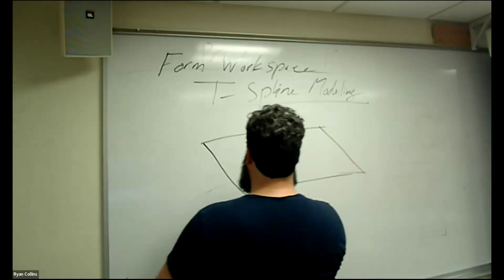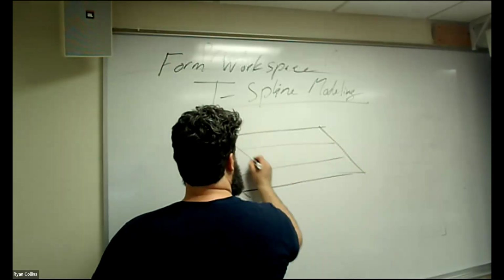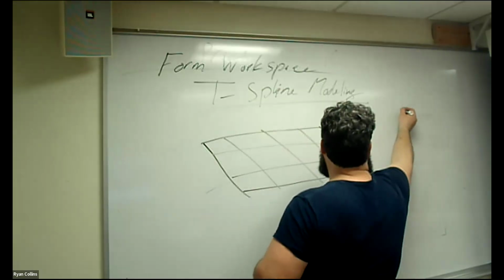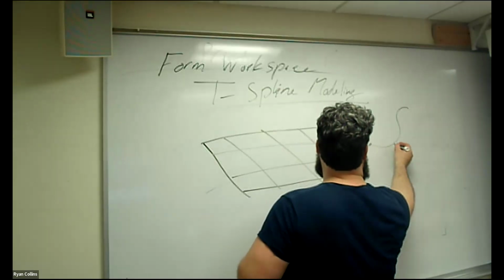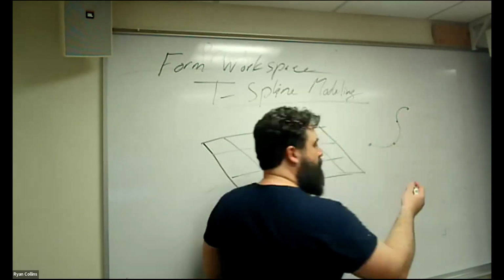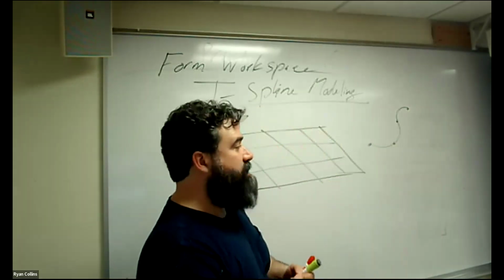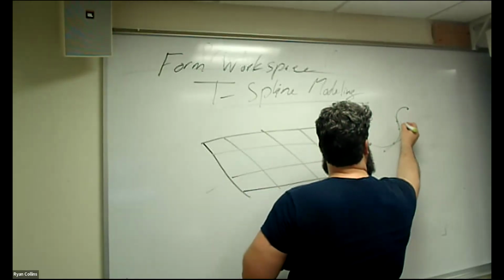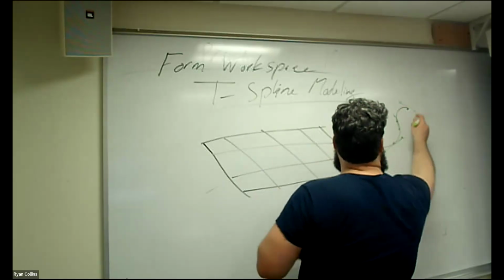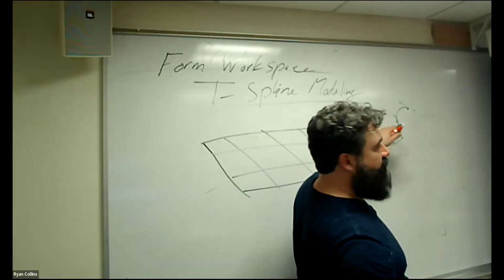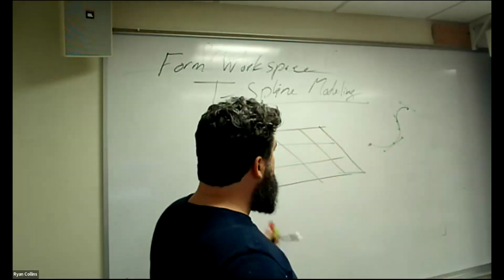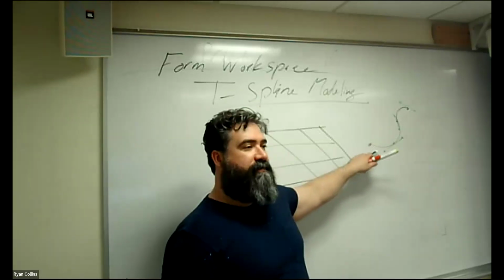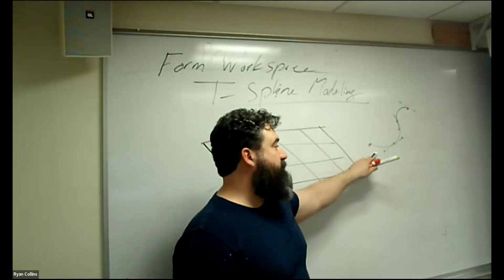and essentially everything is a spline. We've talked about and used the fit point spline, which is the curve shape where you create points and create curves based on that, where you also have the benefit of things like the handlebars, which allow you to alter everything, either the size of the curvature, the depth of the curvature, things like that. T-spline modeling is a bit different, but it's still based off of these spline modeling computations.